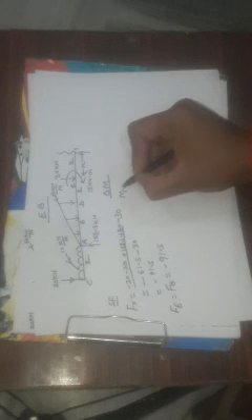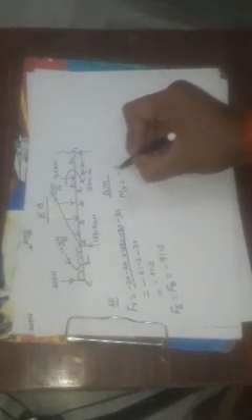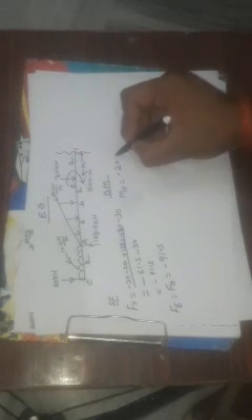This value is again independent of x. Then for x equal to 0 and for x equal to 2, at both points Fe will be equal to Fb, and this is equal to minus 91.5. Now write the equation for bending moment. Mx will be minus 20, the distance is 6 plus 2 plus 2, that is 10, minus 20 into 10 plus x. Minus 20, the total weight of the UDL is at a distance of 1 meter from A.